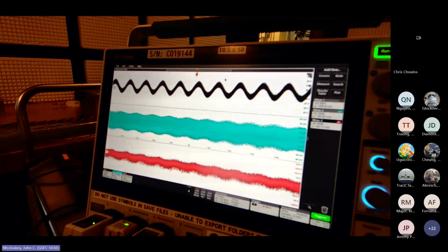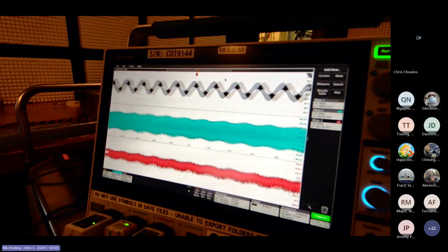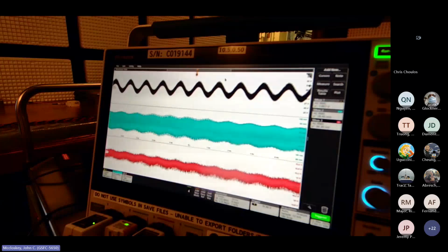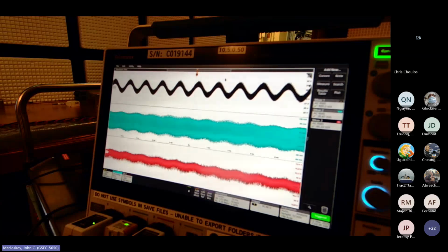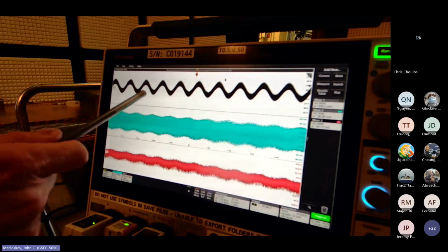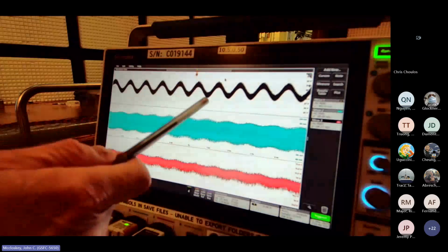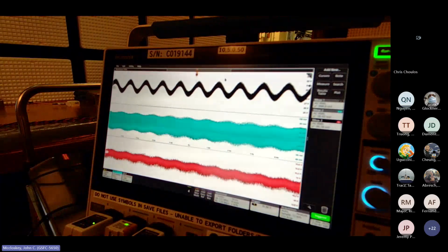Right, the power converter is sampling the input. It's sampling a 28 volt DC level at 400 kilohertz, and it's adjusting, and it's pulse width modulated. It's adjusting the pulse width to give you the desired plus minus 15 volts at the output within the tolerance specified, and you're getting more into the frequency range where that control loop is more effective. So by design, that's exactly how our power converter is working. It's sampling at a much higher frequency than this injected ripple of 1 kilohertz.